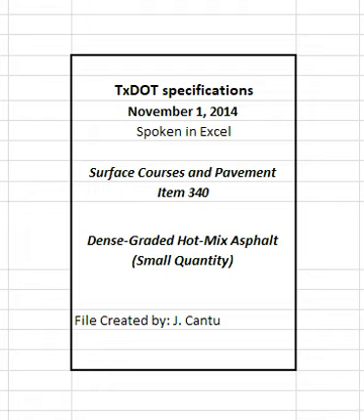Use tamps to thoroughly compact the edges of the pavement along curbs, headers, and similar structures and in locations that will not allow thorough compaction with rollers. The engineer may require rolling with a trench roller on widened areas, in trenches, and in other limited areas. Complete all compaction operations before the pavement temperature drops below 160 degrees Fahrenheit unless otherwise allowed.